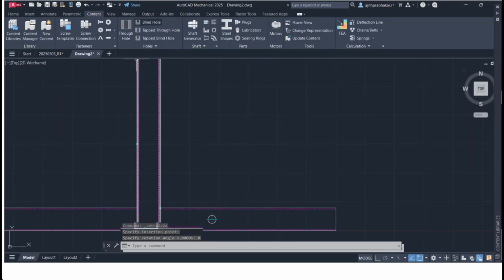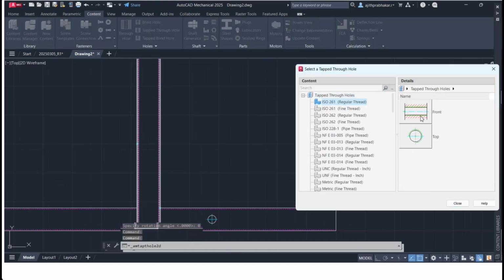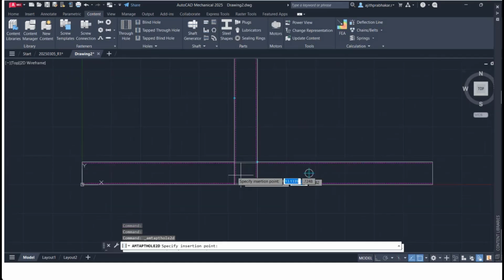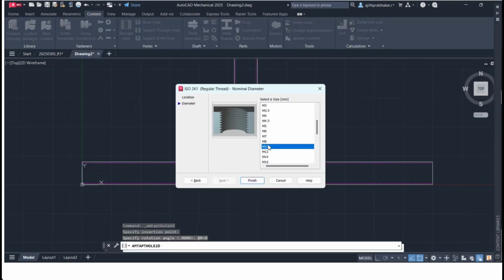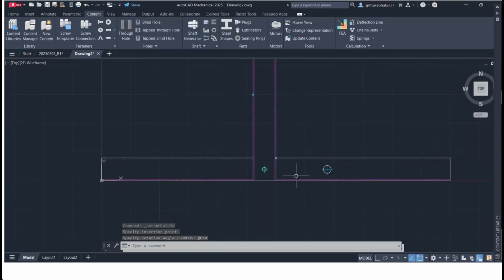It is not just the normal hole. I can also give a tapped hole for any set of dimensions. So why do we mention that? Why do we want to create this? I'll explain that in detail shortly. That could be M10. Yes, you can find there are two different types of holes created in a single strip, and now we are going to place a common fastener